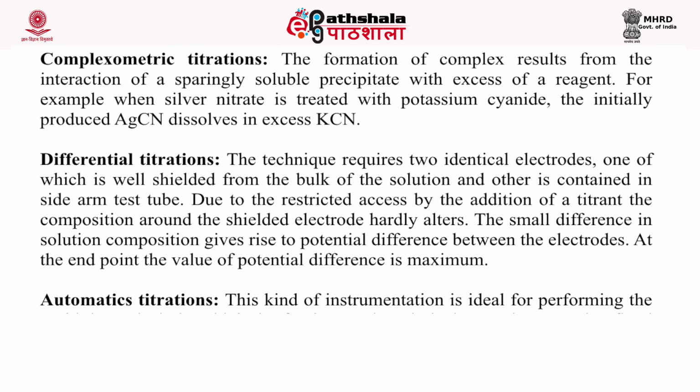Automatic titrations. The automatic titrator is provided with 2-point auto calibration and standardization. The instrument is capable of displaying pH and millivolt of the sample with temperature compensation.